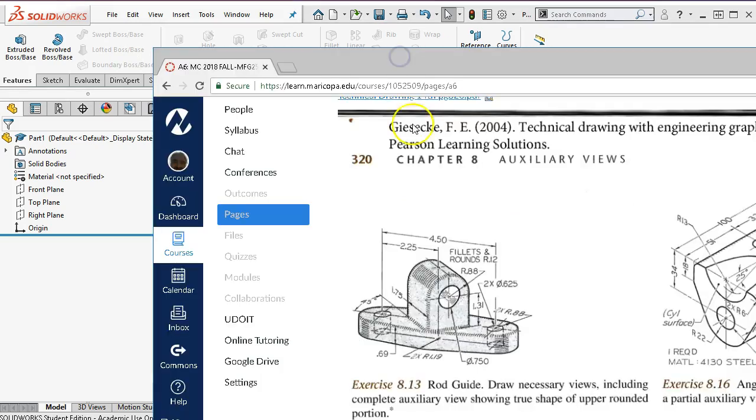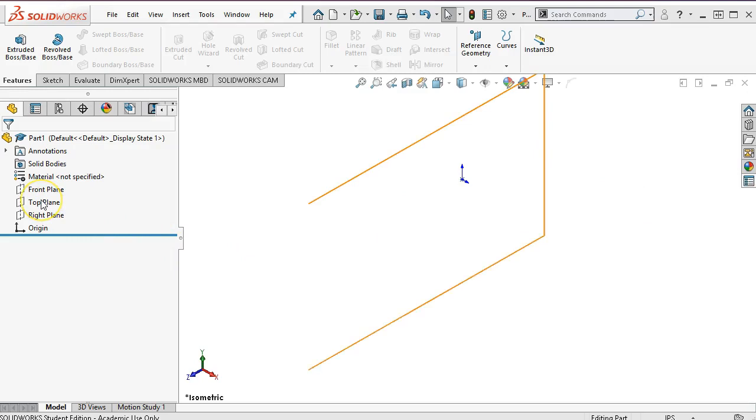All right, so looking at my geometry, we're going to generate this base first. It has symmetry, and we can put the origin at the bottom center of the part and utilize that symmetry to our advantage. All right, so radius of 1 3/16, 1.19, and then thickness is 11/16, 0.69, and the radius at the end is 7/8, 0.88. Okay, so fly that out of the way, and that'll be the first item that we focus on.